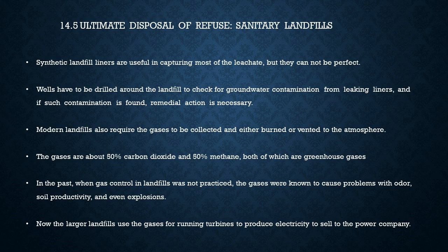Synthetic landfill liners are useful in capturing most of the leachate, but they cannot be perfect. Wells have to be drilled around the landfill to check for groundwater contamination from leaking liners, and if such contamination is found, remedial action is necessary. Modern landfills also require the gases to be collected and either burned or vented to the atmosphere.